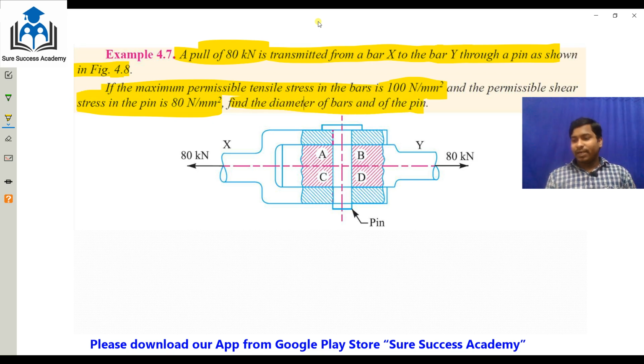This is the main thing: whenever you are doing such problems, you should know which is the resisting area. Shear stress acts parallel to the cross section, and tensile stress acts across the cross section. So in that way, what is happening?